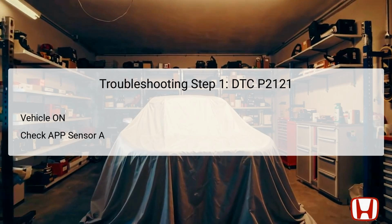Consider the specific voltage readings. If it is less than 0.32 volts, this indicates a clear failure worth investigating further. A response of yes would prompt the technician to proceed to step 3, validating the failure, while no would indicate that the issue may not be definitive, directing them to step 2 for further inspection.